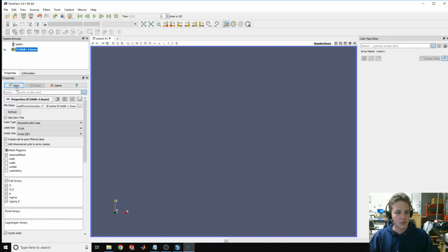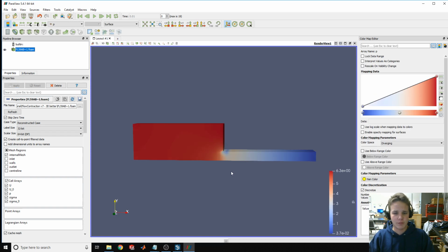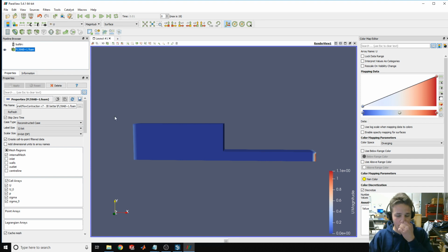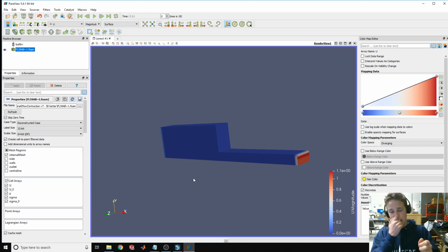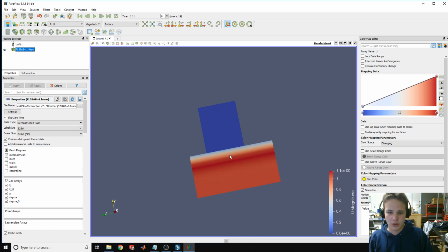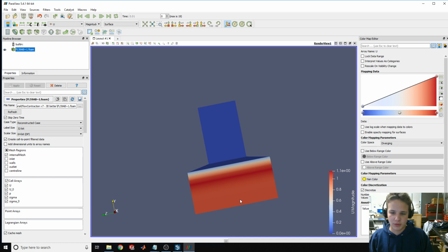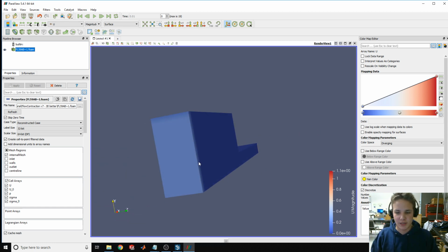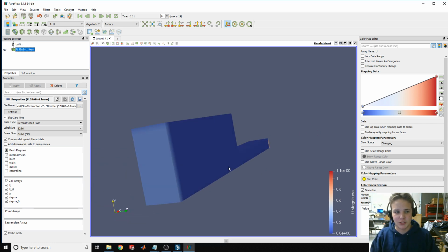Common mistake. So I'm going to open, and this was solved three-dimensionally, and I'm going to go into U. You can see that with the 3-dimensional case, you know how I had the empties to make it 2D? I made those simply walls. So now you can get a cross-sectional view of the flow. And it's kind of interesting how it's going around, I'd say 1 goes to 1.1 and goes to around 0.6. And you can see on the other side it's basically all 0.5 because that's the inlet condition.